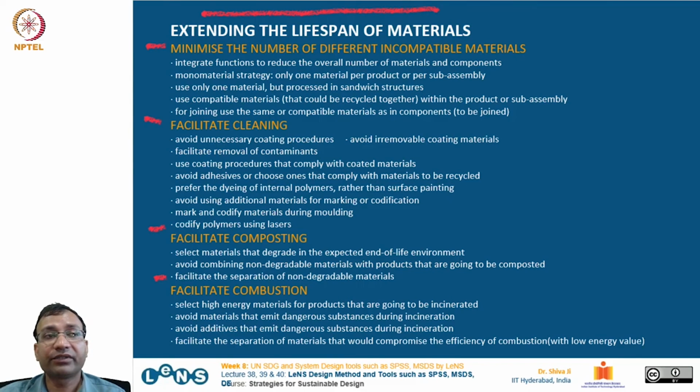For the strategy of facilitating cleaning, avoid unnecessary coating procedures. Avoid irremovable coating materials which cannot be taken out. Facilitate removal of contaminants. Use coating procedures that comply with coated materials. Avoid adhesives or choose ones that comply with the materials to be recycled. Prefer the dyeing of internal polymers rather than surface painting. Avoid using additional materials for marking or codification.